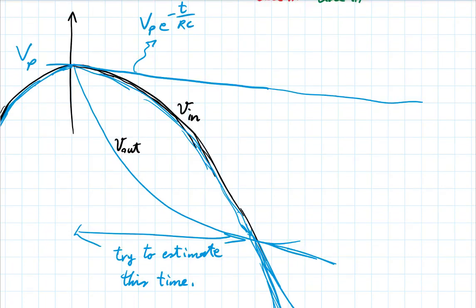So the question is to maybe elaborate on this a little bit. If the diode is off, then the output is basically a capacitor with some charge in parallel with the resistor, right? So it would start decaying exponentially. You have a first-order differential equation to solve, all the standard things, right? But imagine that the RC time constant of this decay is extremely fast.